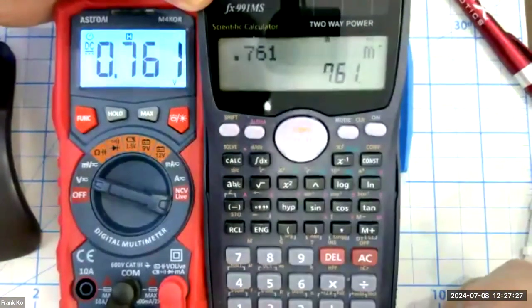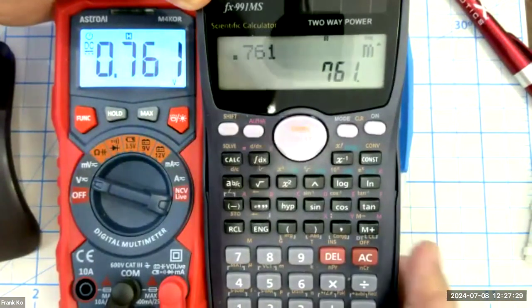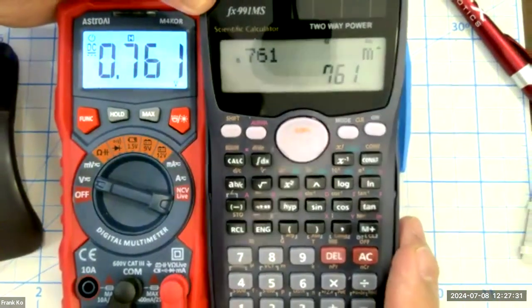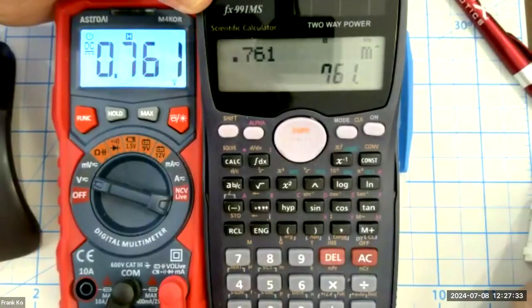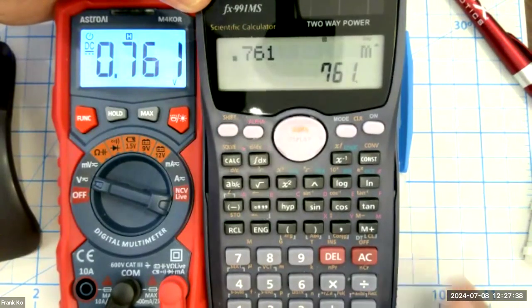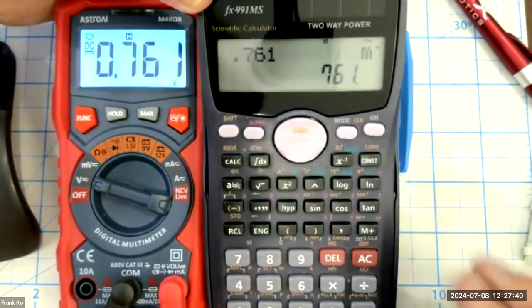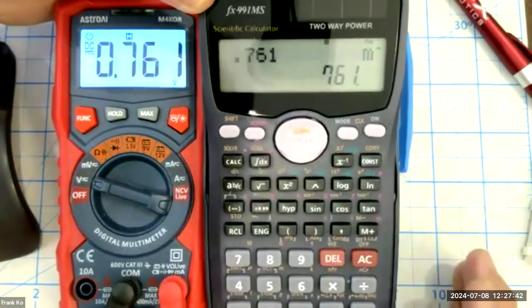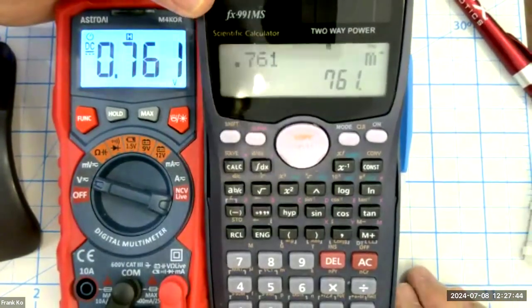So it's pretty darn close to our calculated 769 millivolts. Our measurement is 761 millivolts, as you recall, because the resistors have tolerance. I have ohms that are scattered in the breadboard itself, and there's a tiny bit of ohms on the wire leads and a tiny bit of ohms on the jumper wires. We're not ever going to be exact, but this is pretty darn close and certainly close enough.